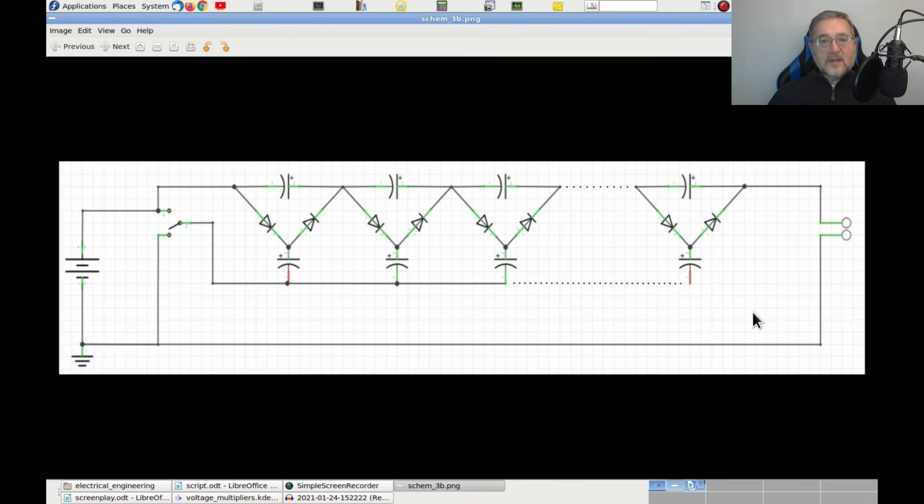And the nicest thing of all is that even if we were building a circuit with a lot of stages, producing a very high voltage, each capacitor does not need to work at that high voltage, but just at the voltage of the power supply. So at the end, this is a low-cost way to obtain high voltages, given that we do not try to extract a lot of current. Otherwise, like we have seen in the lab with the first circuit, the output voltage will start dropping.